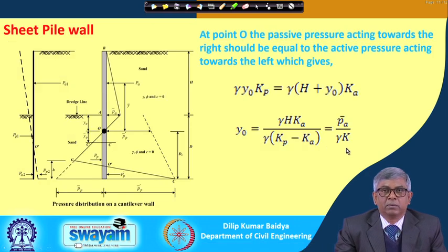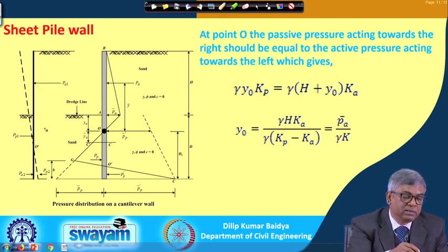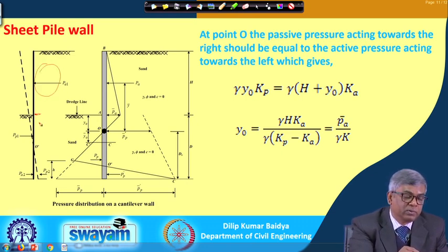Next, as I have shown before, the flexible retaining wall, and you can see the typical deformation. The ground mark is here and it is a cantilever and this is embedded, then the wall typically rotates like this. If it rotates like this, then what happens? This portion is active and this portion is passive, and again this portion is active.